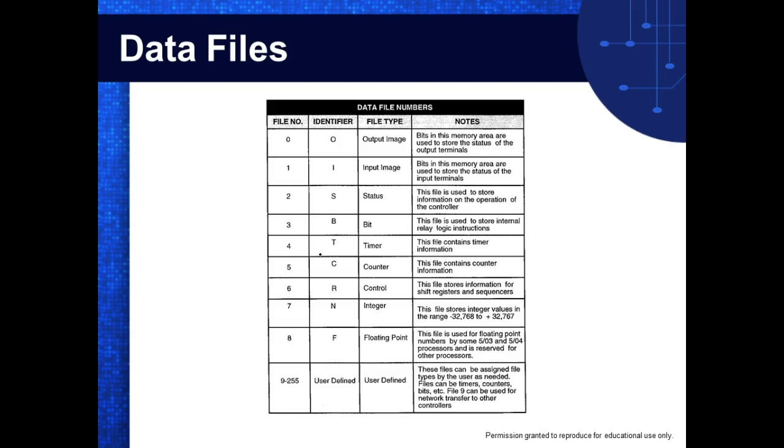Everybody okay? And then all these other ones are what? Fine. Yeah, these are user defined, so it means you what? You define. Yeah, you define them. So I might come up and use like an F22. Well, an F22 would define that register as a what? A floating point register. Right? You understand that? And how many of these are available will be determined by your PLC. Everybody okay? Lost anybody?